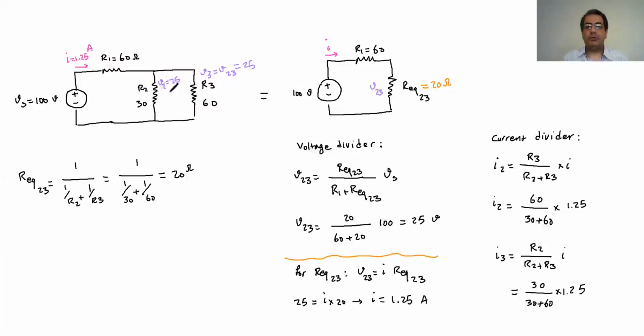Also, because we already have the voltage, we also could have used the Ohm law to find the I2 and I3. So this is the usage of them. You can see it is the same concept, just using a different way, but it's the very same concept of doing the voltage divider, current divider. Sometimes it's going to be easier to use the voltage and current divider. Sometimes it's just easier to directly use the simple parallel and series concept to find the voltage and current.